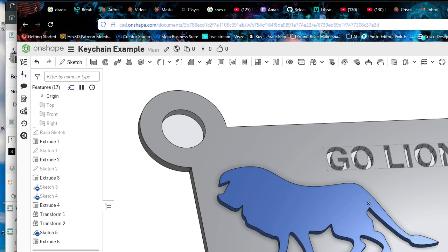Yeah, it does. So just choose, what is that, sketch 5? Try just clicking on sketch, just sketch 5. And then transform. Or no, because you're in sketch mode now. Selecting, it's going into sketch mode. So try clicking, don't double click, just click it once, and then go to transform. See if it lets you actually. So then instead of translate by line, do scale.